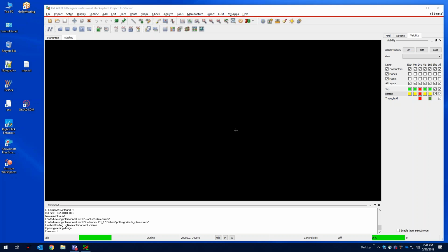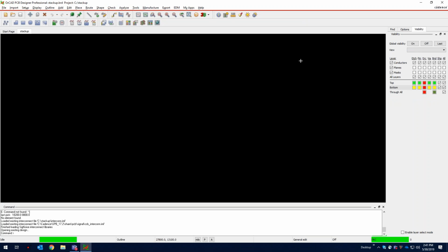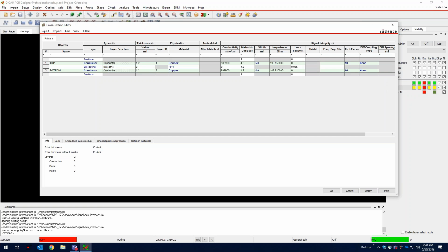Okay, thanks, Matthew. I'm just going to show a demonstration here of the Stackup editor in PCB Editor. As Matthew had mentioned several times, when you're designing a board, it's very important to work closely with the board manufacturer to see what requirements they might have for minimum trace widths, trace spacing, number of layers that they can build, and for the right price. Knowing this information up front can avoid any kind of potential design rework down the road.